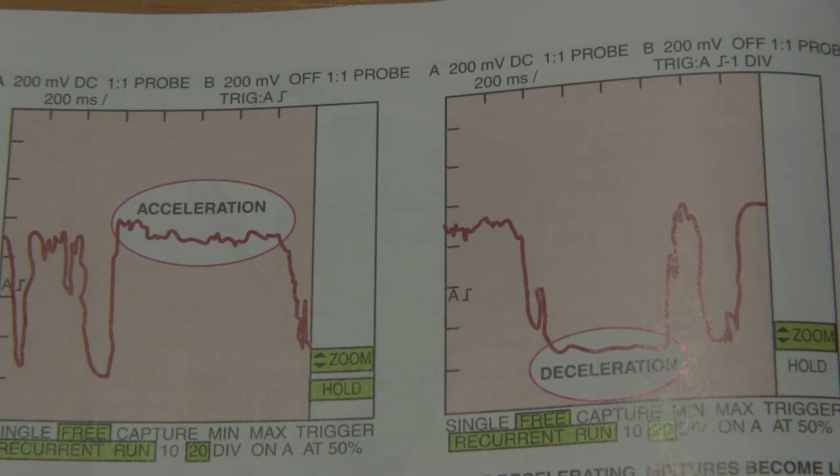those are rough numbers. And so what the manufacturer does on a narrowband car, since the oxygen sensor cannot actually see that air-fuel ratio, it's guessing. It's literally guessing as to what the air-fuel ratio is based off of previous engineered dyno tests that they've ran, and then they've pre-programmed into that vehicle.